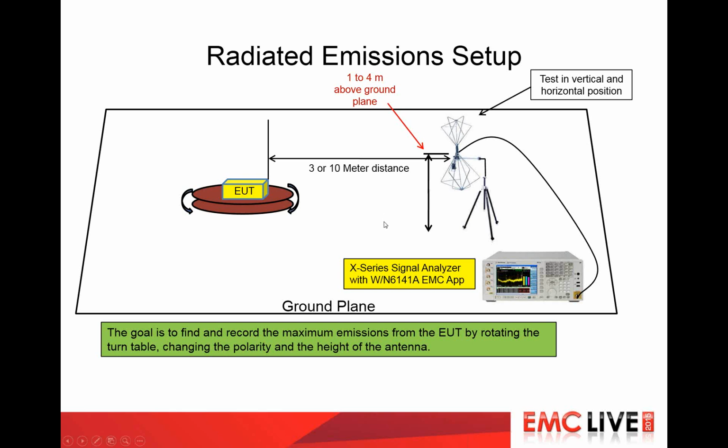So for pre-compliance testing, what we recommend is that you set up 3 meters from the device, 1 meter off the ground.